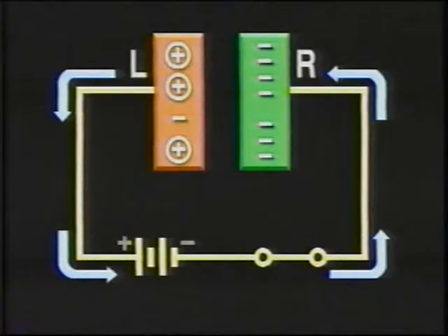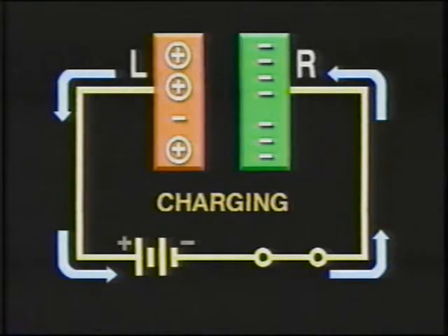It's important to realize that during this process, free electrons do not pass through the dielectric because of its insulating characteristic. Free electrons travel through the connecting leads, source, and switch only. This forced movement of electrons from one plate to another by a voltage source is known as charging. The electron flow is referred to as a charging current.